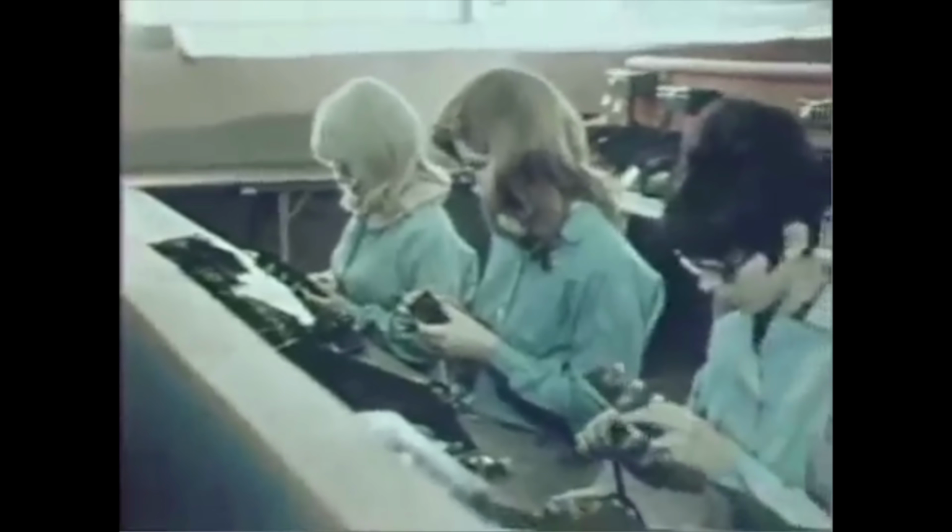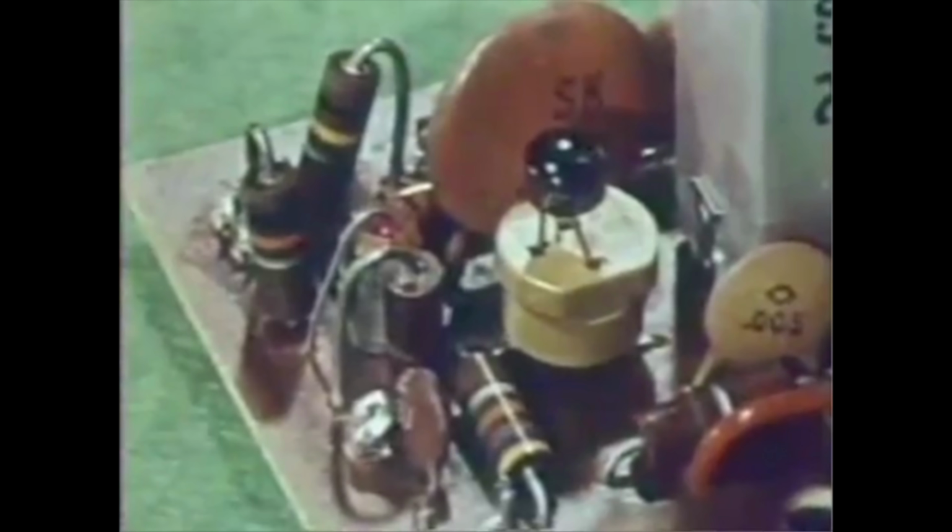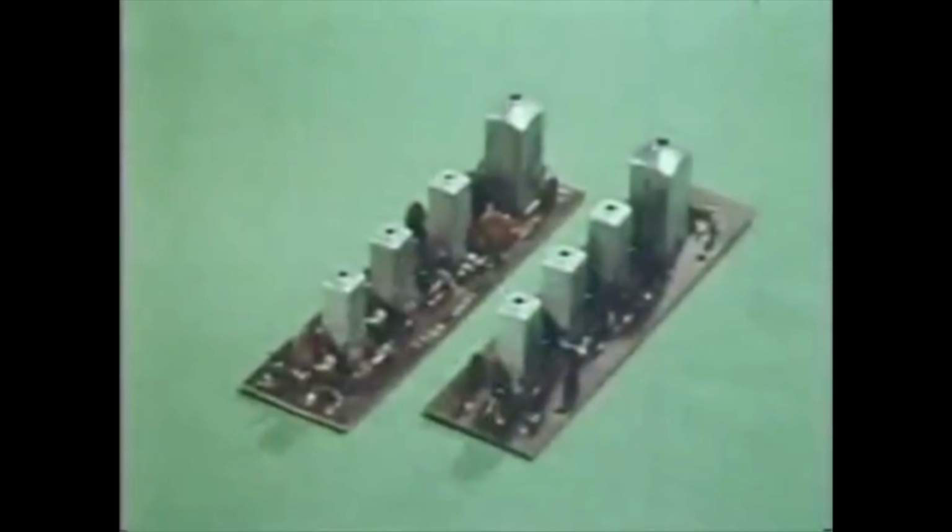This is the Model 388 AM/FM stereo receiver built by H.H. Scott. It's only one of a new line of hi-fi components in which linear integrated circuits replace discrete transistors. Scott engineers have chosen ICs for one specific purpose: better performance. More stations can be pulled in with less noise and interference. Weak stations become loud and clear, and outside interference is drastically reduced. But there are other benefits too. A total of 37 discrete components in the receiver's IF strip have been replaced by only 4 ICs. This new approach to circuit design promises even more dramatic new products from the people at H.H. Scott.